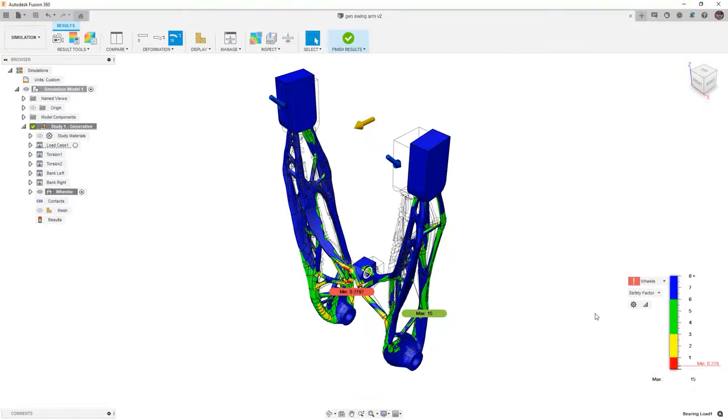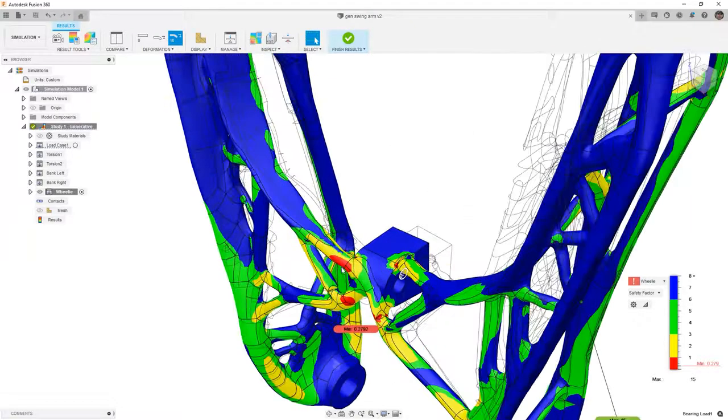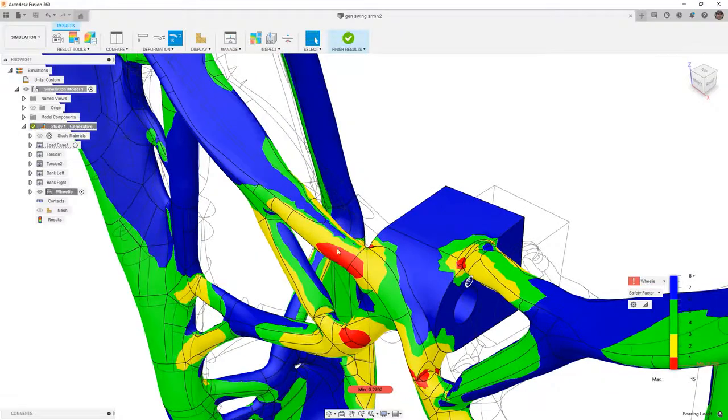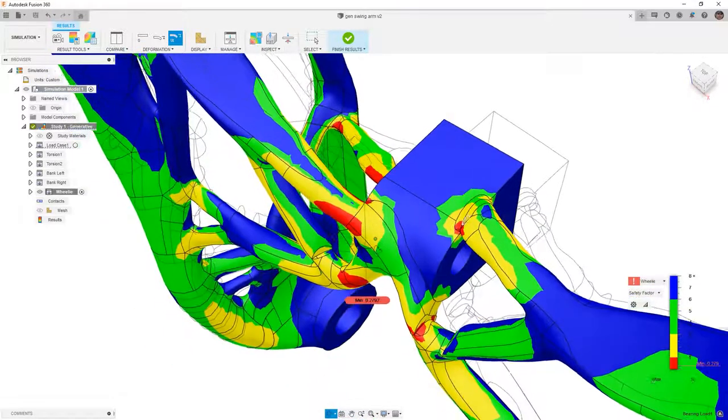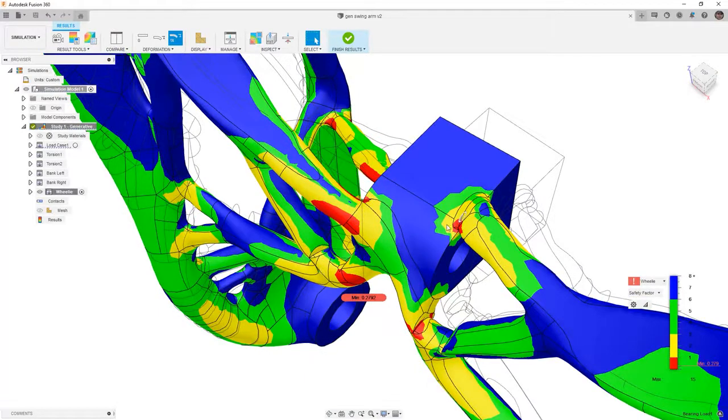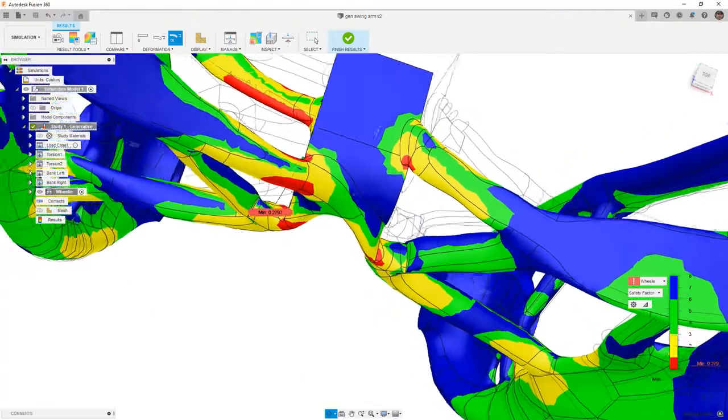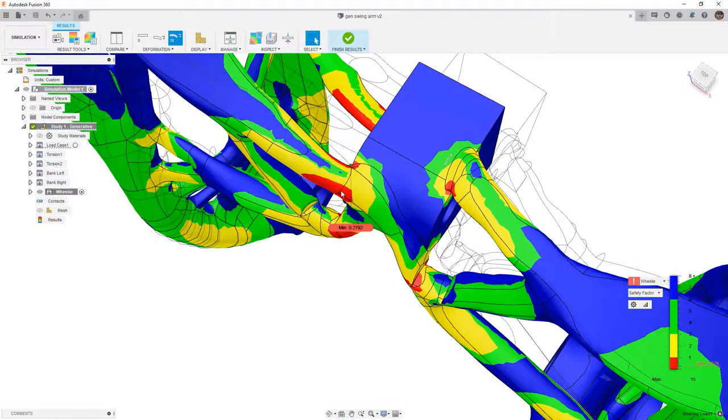One thing that we need to understand about the difference between our exported design and the simulation results in generative design is the fact that all of our preserves were converted to mesh bodies and included in the overall study. So for the final design, the mesh bodies and the T-spline body that was created are then combined, which means that we have sharper intersections than we did in the original mesh. So we can see this, in this case, we have these high areas of stress concentration.